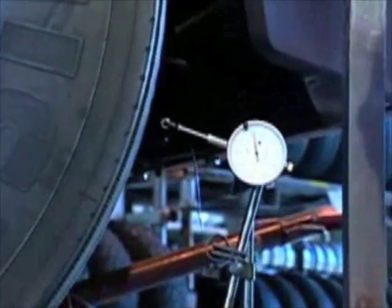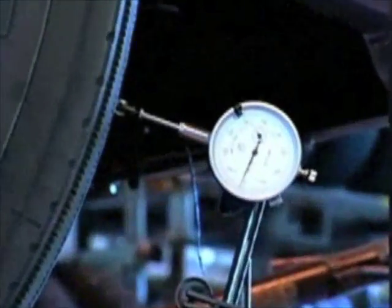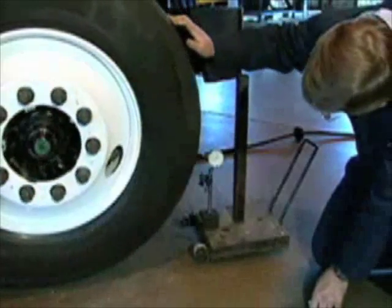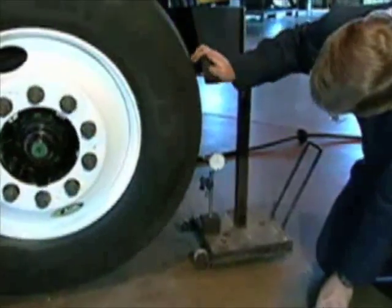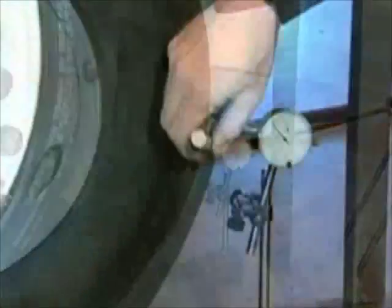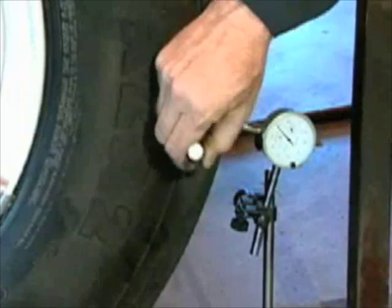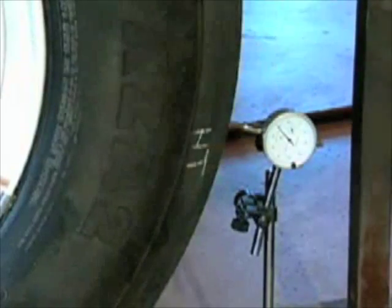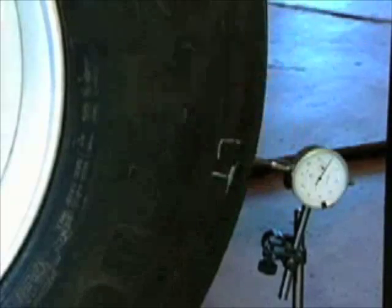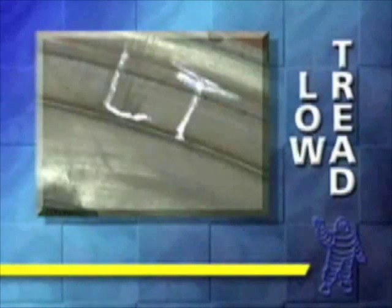the dial indicator at a 90-degree angle to the surface of the tread in the center of the front tire. Slowly rotate the tire a few revolutions to obtain the high and low readings. The difference is your radial runout. Mark the position of the high and low reading on the sidewall of the tire in crayon. For this purpose, we will mark it as HT and LT, which stands for high tread and low tread.